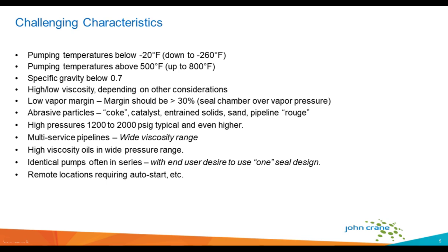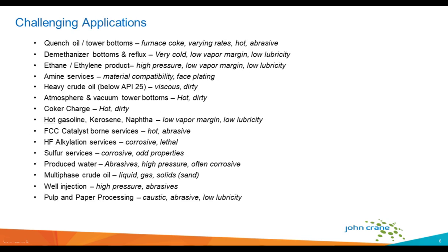Abrasive particles, high pressure, 1200 to 2000 psi, and the pipeline could be higher than that. Multi-service pipeline, wide viscosity ranges, and high viscosity oils and wide pressure ranges. And in the pipeline, you have identical pumps often in series, which means that multiple pumps will have the same mechanical seal, however, different application or the pressure-wise, and remote location requiring auto startup.